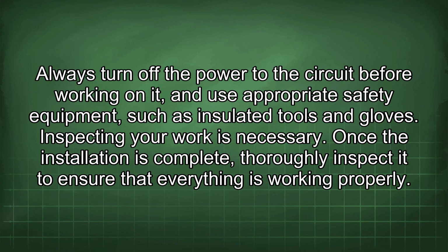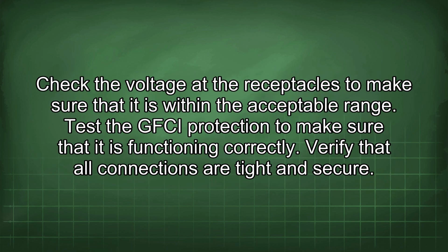Once the installation is complete, thoroughly inspect it to ensure that everything is working properly. Check the voltage at the receptacles to make sure that it is within the acceptable range. Test the AFCI protection to make sure that it is functioning correctly. Verify that all connections are tight and secure.